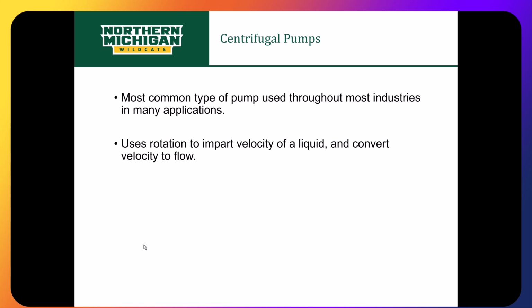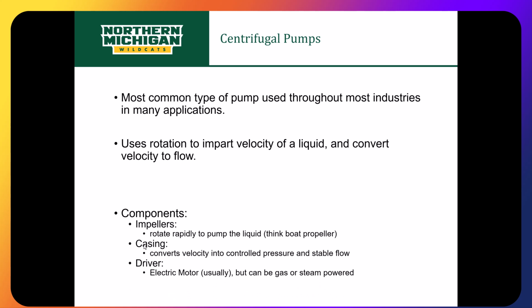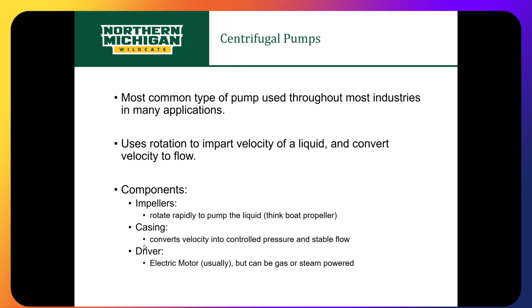Pretty simple, pretty straightforward. They're just like a centrifugal fan. When we talk about that in the airflow portion of this course, they operate in a very similar fashion. We basically have three major components to them: an impeller, a casing, and a driver. The impeller is the portion that rotates and actually pumps the liquid, thinking like a boat propeller. Your casing converts that velocity into controlled pressure to stabilize the flow. And then you have a driver, which is that electric motor, usually gas or steam powered.